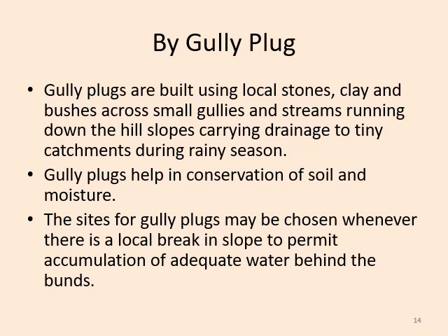So this is where the catchment area is small and the contour is not uniform, with upward and downward hill slope. In this context, gully plugs are built with local stones, clay and bushes. Gully plugs help in conservation of soil and moisture in the soil.